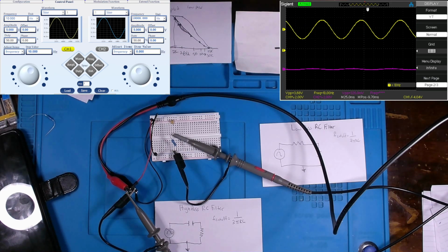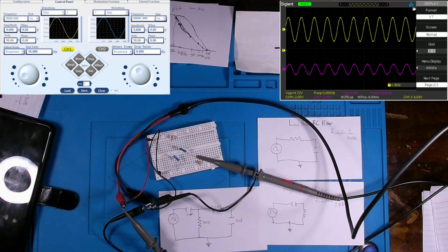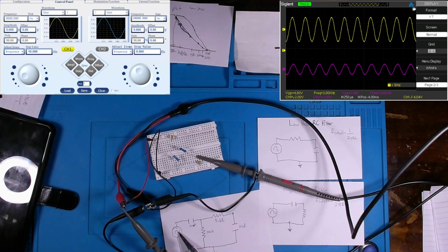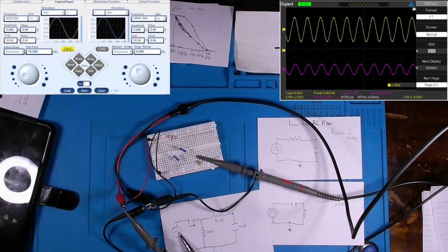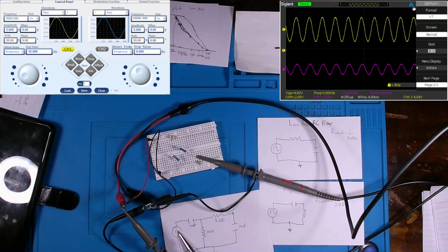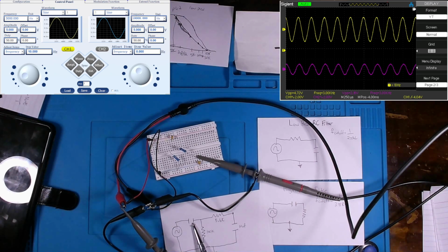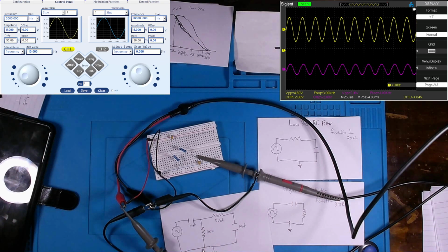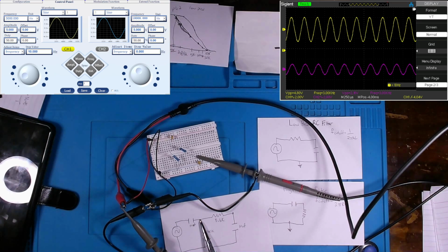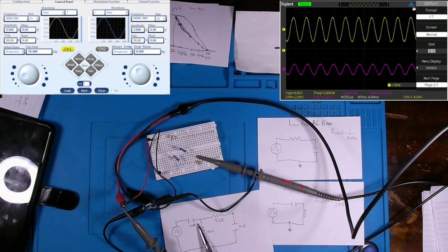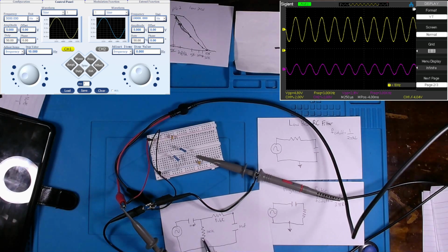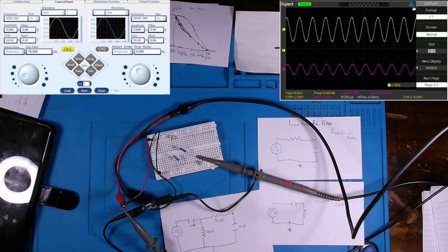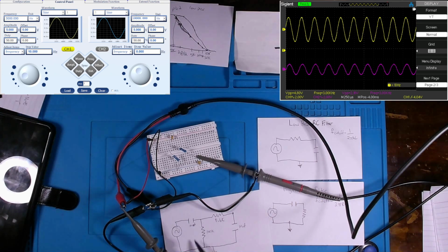Let's try to put these two together. Okay, so what I've done is essentially taking our 5-volt AC input, starting value 3K hertz. Now put our 10 nanofarad cap here, followed by a 100K resistor tied to ground. And then in series with this capacitor, we got our second circuit, two circuits within this entire circuit, which we call branches or whatever the term was that we learned in DC theory.